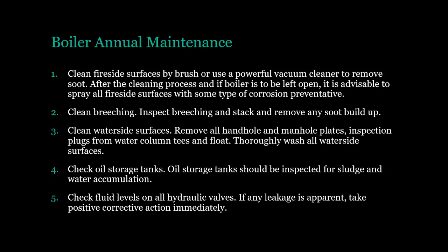Clean waterside surfaces. Remove all handhole and manhole plates, inspection plugs from water column tees and float. Thoroughly wash all waterside surfaces. Check oil storage tanks. Oil storage tanks should be inspected for sludge and water accumulation. Check fluid levels on all hydraulic valves.